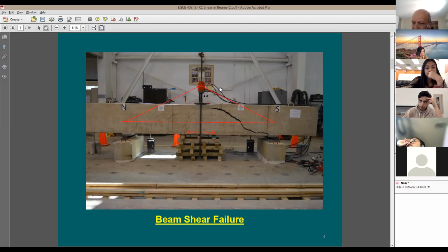Once you stay away from the middle of the span, the flexure stress is going to reduce and you're going to have fewer cracks. You see these flexure cracks get reduced. But this big crack here is not really due to flexure. This crack is due to shear.